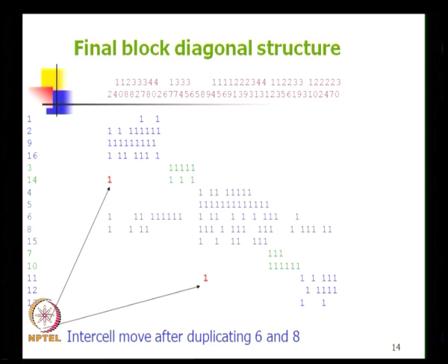Now when we start creating or planning the required capacity of each of these cells that have been created, we have to find out whether one machine is enough to meet the demand of all the components visiting that particular cell, or do we need more than one machine of a type simply because of the capacity requirements. In other words, capacity requirements have to be calculated based on which the number of machines of a particular type going to a cell will be determined.